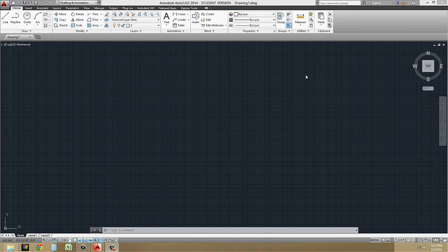Now in the professional world, there are two ways of doing this. One is to have all of your information in model space and to create these layout tabs as each one of your sheets. That has its pluses and minuses. Its plus is that it keeps everything in one file. The minus is that you cannot have multiple people working on an AutoCAD file when it's open.